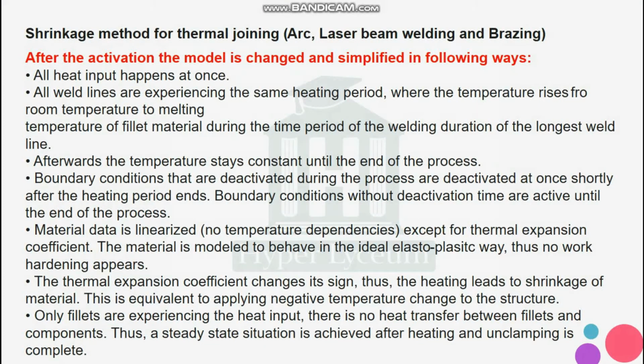Boundary conditions that are deactivated during the process are deactivated at once shortly after the heating period ends. Boundary conditions without deactivation time are active until the end of the process. Material data is linear temperature dependent except for the thermal expansion coefficient. The material is modeled to behave in the ideal elastoplastic way, so no hardening appears.